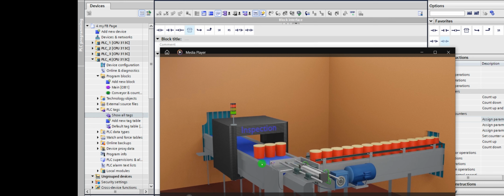Now there's a sensor here. There's a proximity sensor here facing this direction to sense the distance between this finished product and where it's going to be situated. This sensor is the one responsible for shutting down this conveyor, to put it on hold. Once this sensor stops this, that same sensor will activate this pneumatic system to push. So this sensor does two functions. One is to stop the movement of the bottle. Another one is to activate the pusher from this pneumatic system. Okay, you now understand the logic.